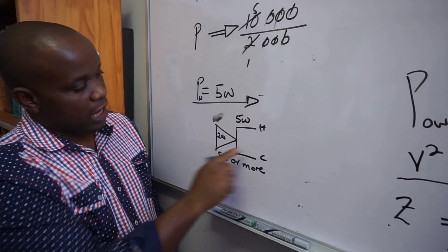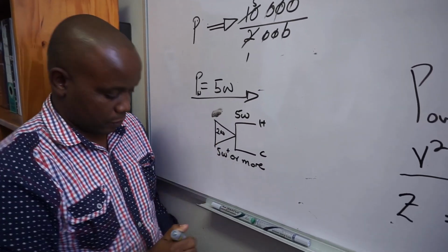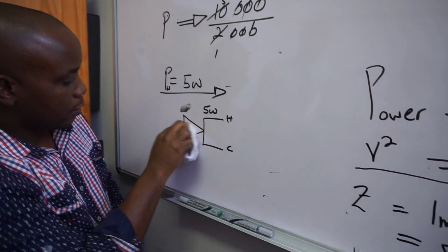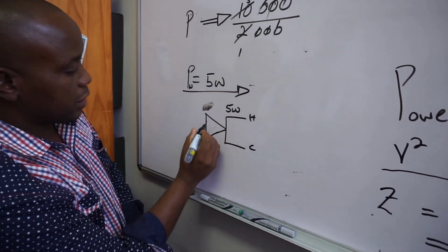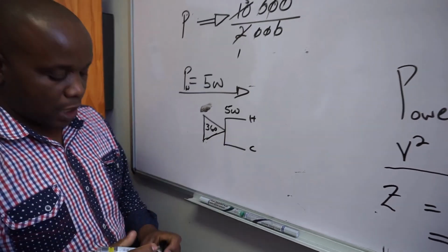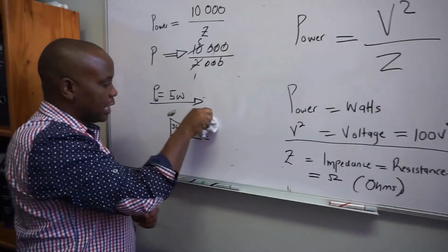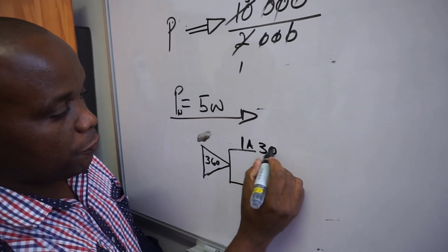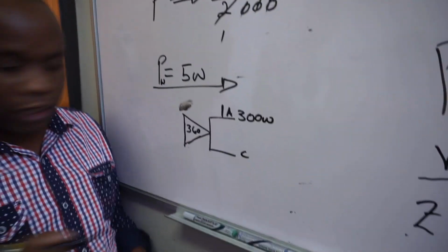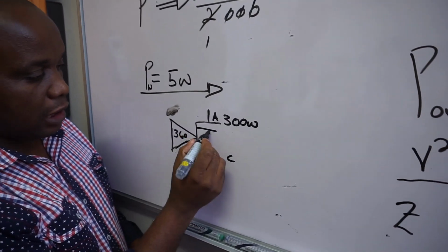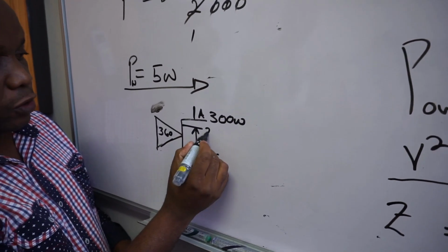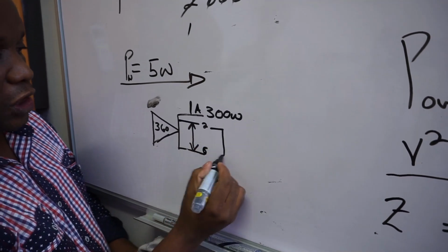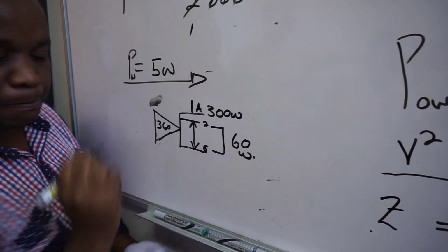Similarly, if I was to have a ZM-104A, for example, with 2 speaker lines, which I'll then just correct quickly for the purposes of our demo. Let us assume this is a ZM-104A rated at 360 watts. And we have measured the speaker line. Out of the first speaker line, we have measured line number 1, it's demanding 300 watts of power. What it then means on a ZM-2000 or a ZM-3000, the left speaker lines from number 2 to number 6 will have to share the 60 watts that's left.